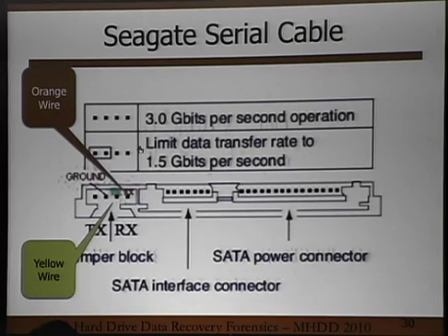You hook up these 2 wires, the orange wire from that list and the yellow wire, and you plug this into a terminal. And you will be able to tell almost all diagnostics problems with Seagates. Whether you understand them or not is a different world. But you can see on a terminal screen what is wrong.